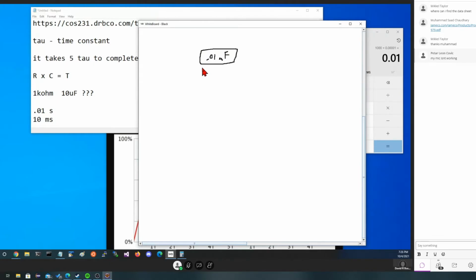They're going to generate an imaginary power. They're not going to be the power that's going to generate heat. So to do this, we have a formula. The formula is 1 divided by little omega C. And that's equal to our capacitive reactance in ohms. And you go, well, that's great. I see the capacitance here, but what the heck is omega? Omega is basically what's called the angular frequency. We can simplify looking at it. We can rewrite this formula, expanding it.